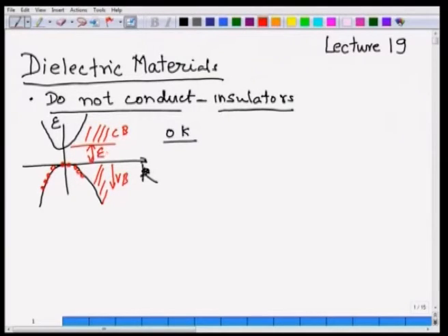This was Eg. So on this side something like Ev and Ec, and a band gap here Eg. Then what happened was that at 0 K, this semiconductor was also an insulator. Why was it an insulator? Because the valence band was completely full of electrons all the way to the top, whereas the conduction band right here was completely empty.